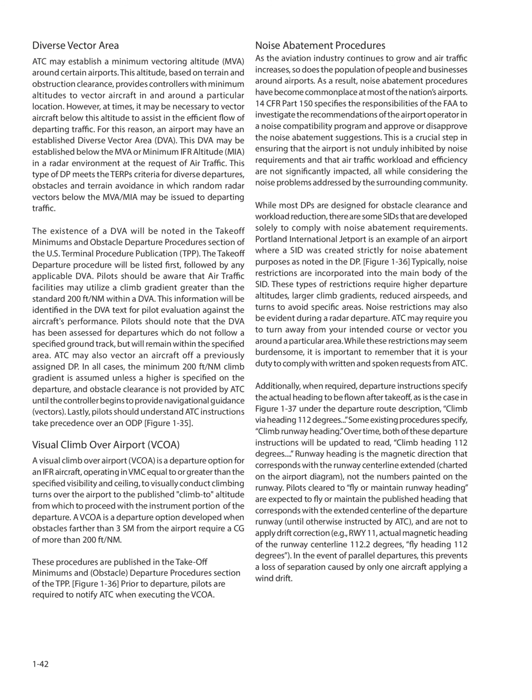Noise restrictions may also be evident during a radar departure. ATC may require you to turn away from your intended course or vector you around a particular area. While these restrictions may seem burdensome, it is important to remember that it is your duty to comply with written and spoken requests from ATC. Additionally, when required, departure instructions specify the actual heading to be flown after takeoff, as is the case in Figure 137 under the departure route description, climb via heading 112 degrees.